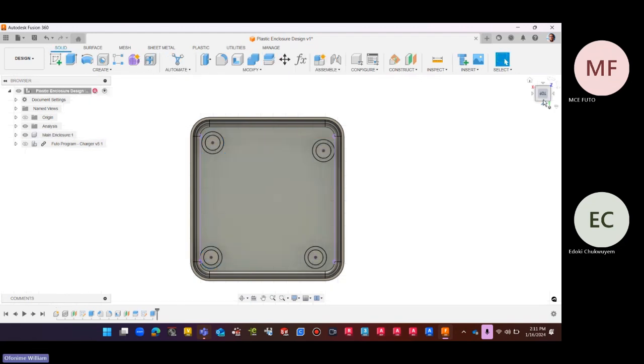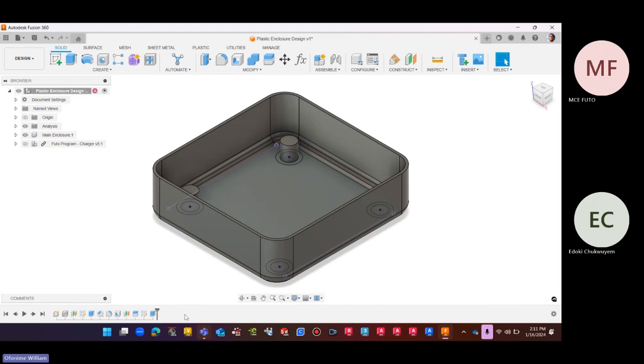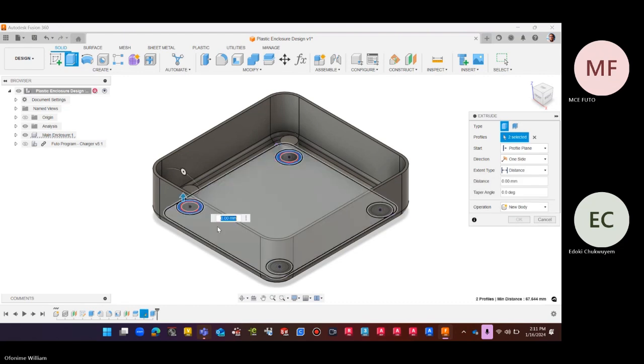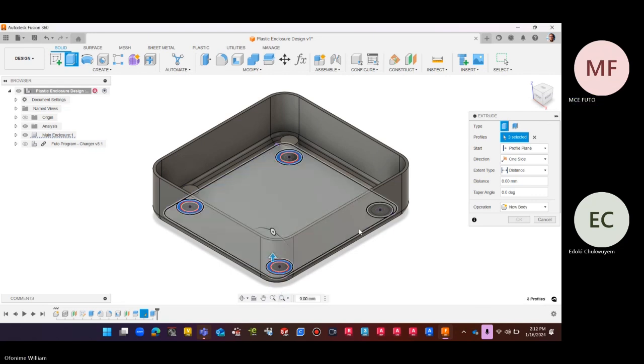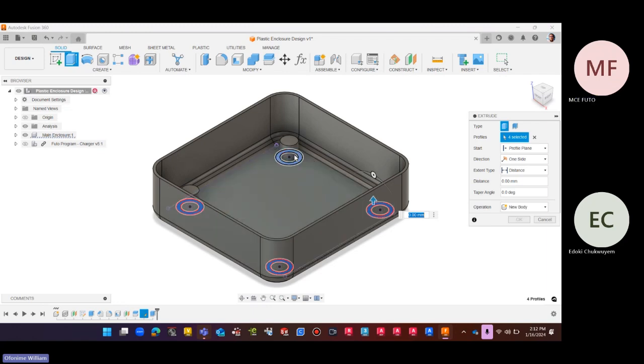Now, it will be weird having some of them big and the rest small. It doesn't make any design sense. So click on this part. Click here. Click here. Now look at what I want to do. I want to select the sketch inside, but I'm obstructed. So you left click on your mouse and hold for a while. It gives you this dialog box, and you can use that to do your selection. It can come in very handy. So I just had to show you.